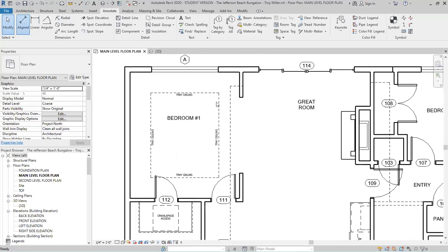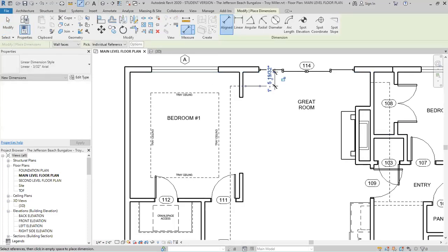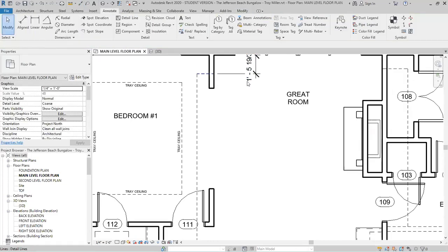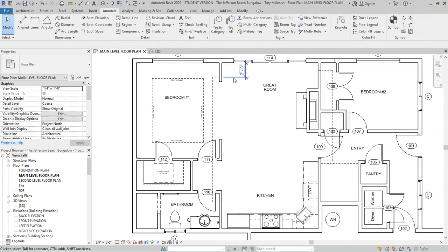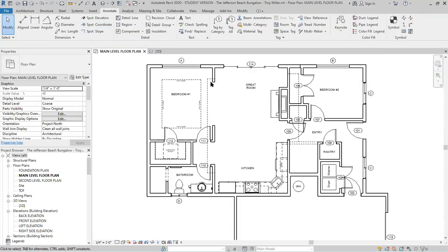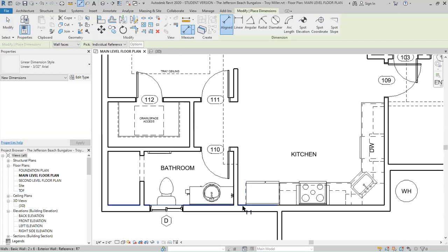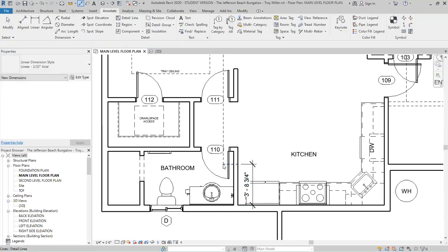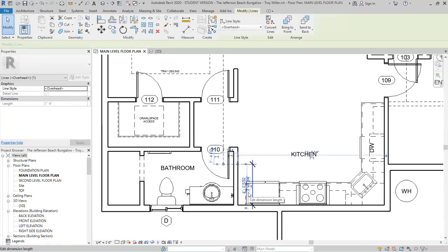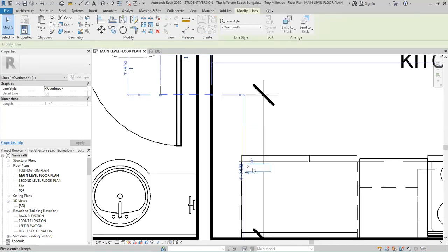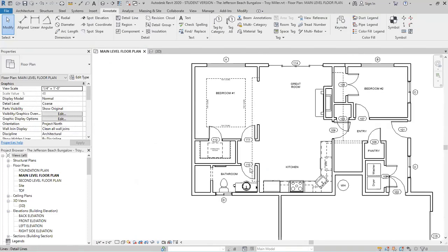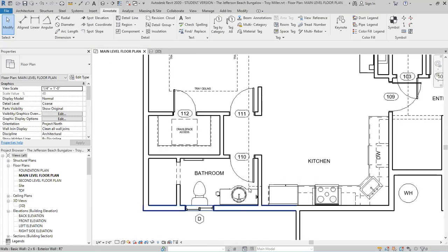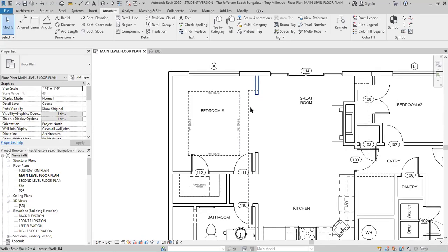So again, I'm going to put in some temporary dimensions. I measured this beforehand, and if I remember correctly, that was 2 foot off of the face of the wall. Once I get that, I really don't need that dimension in there. Let me go ahead and put that dimension again over here, which will be 2 foot. And it should be off it right there. Perfect. So the reason I waited to do the vault line is that, assuming this overhead line there is in the correct position, my vault is exactly dead center of this line.